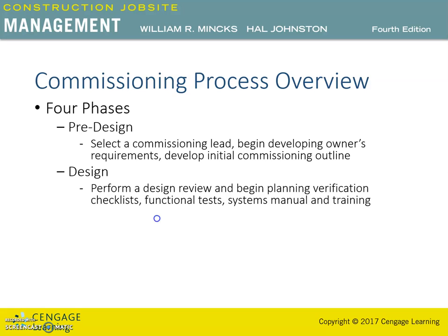design phase: commissioning meeting, if pre-design meeting did not occur, perform commissioning focused design review, update commissioning plan, develop commissioning requirements for the specification, begin planning for verification checklists, functional tests, systems manual, and training requirements.